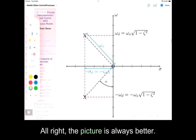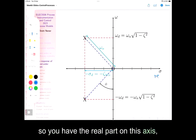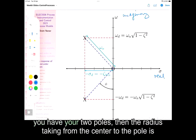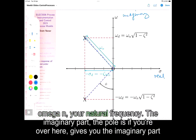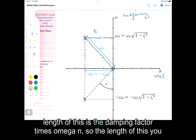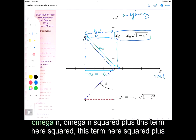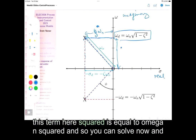All right. A picture is always better. So if you plot the poles on the complex plane, with the real part on this axis and the imaginary part on this axis, and you have your 2 poles, then the radius from the center to the pole is omega n, your natural frequency. Going up here gives you the imaginary part, and going down here gives you the real part. So you can do the algebra. The length of this is the damping factor times omega n. You can use Pythagoras' theorem to come to this equation. The hypotenuse is omega n, so this term squared plus this term squared is equal to omega n squared.